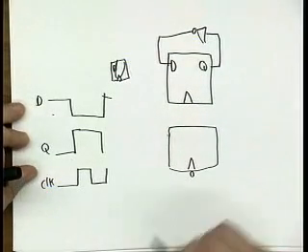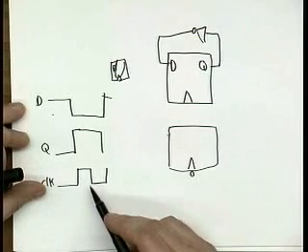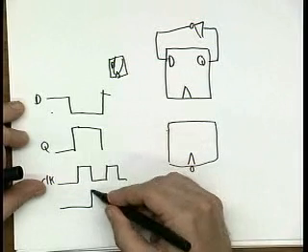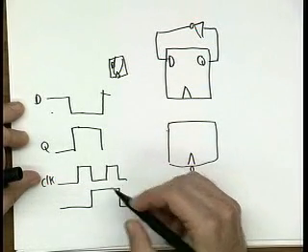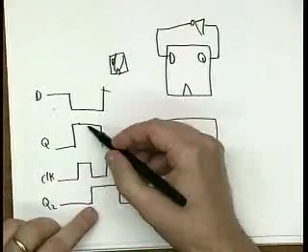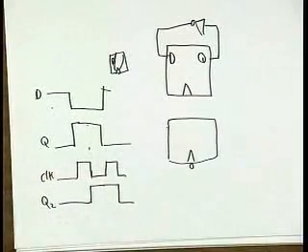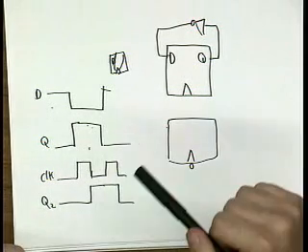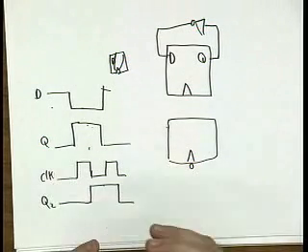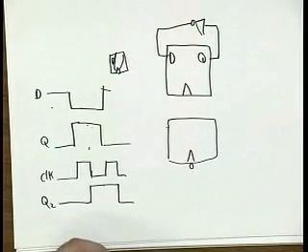the clock? So now it would be responding on the negative edges of the clock. So its waveform would look like that, switching on the negative edges. And if you compare, call that Q2, you compare this to this, you can see that they're 90 degrees phase split. And there's a natural, accurate 90 degrees phase split. This is probably the most common way now that phase splits are generated, because they're nice and accurate, and their sort of logic is so fast now that you can build these at really low power.